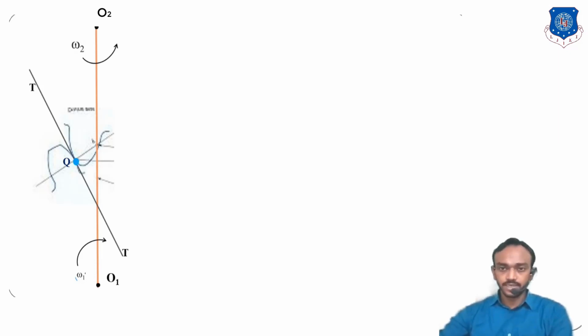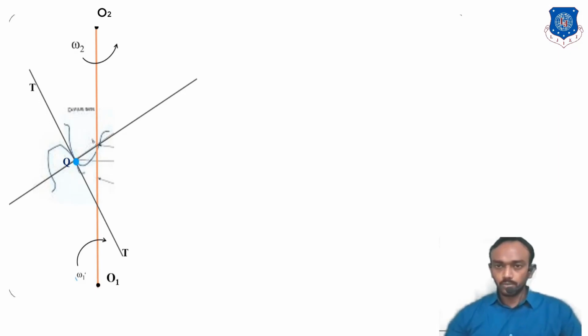It is a common tangent, as you have already done in engineering graphics. At a tangent you can also make what? A normal. So there is a tangent and a normal at Q, where Q is the contact point between the teeth. Now we draw perpendiculars to the common normal from O1 and O2, and name the feet M and N. Here on the figure you can see that TT is the common tangent, and MN is the normal to the contact surface at Q.